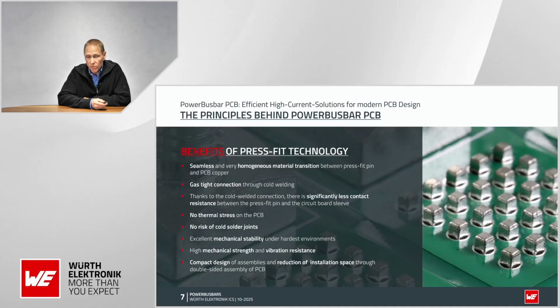Since this is a cold welding process, you have no thermal stress on the PCB and so have no risk of cold solder joints. This connection method has an excellent mechanical stability and high mechanical strength, and it is proven in many vibration tests that we have done with our systems. Also, it is possible with the massive press fit technology to create a compact design, because you can use press fit components on both sides of the PCB, and so you can reduce your installation space.